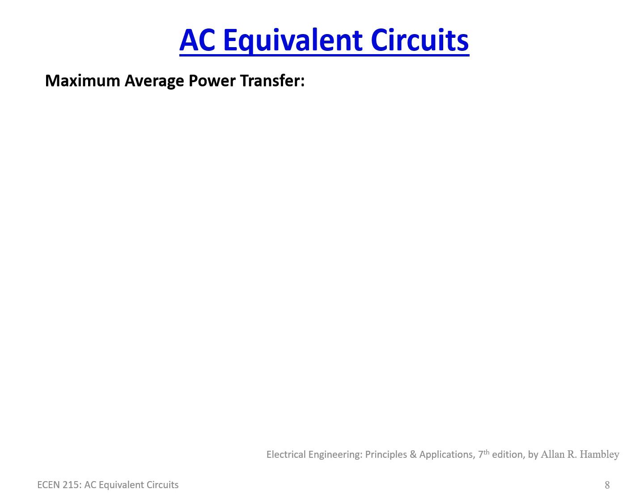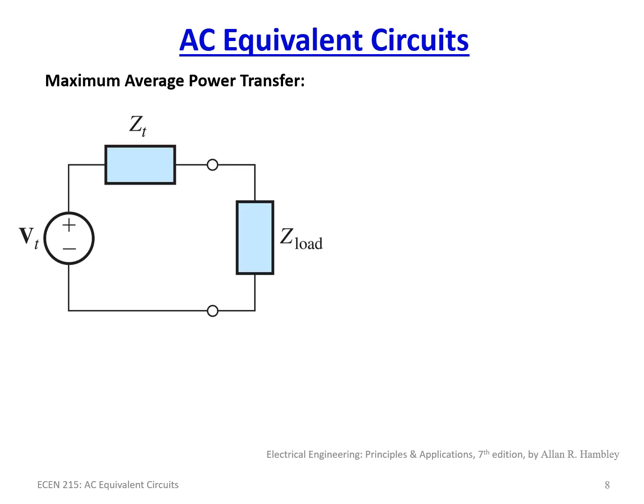Now we have a Thevenin equivalent. Now we have a circuit that has VT and ZT in it. And so the natural instinct would be, what is Z load? Naturally, when you first look at this, your answer is, well, obviously Z load must be equal to ZT, because RL was equal to RT, so by comparison it's probably the same thing.